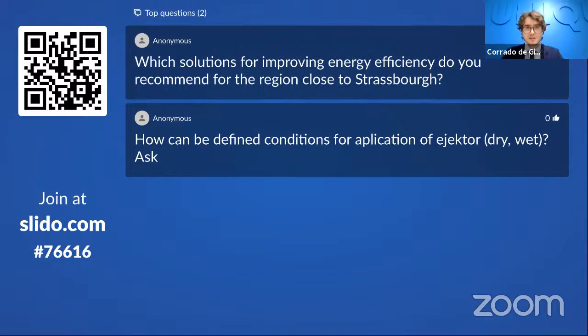In this case, in our work we have considered ejectors, vapor ejectors, so not liquid ejectors, and using also the overfed evaporator. So in our cases, we have used correlation from literature for the vapor ejectors, and in our case, they sucked the vapor outside the empty pressure receiver and recovering part of the expansion work.